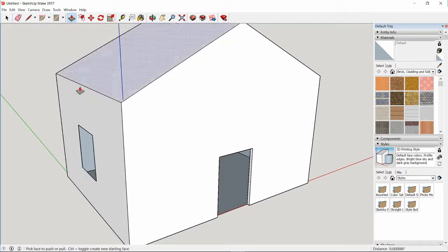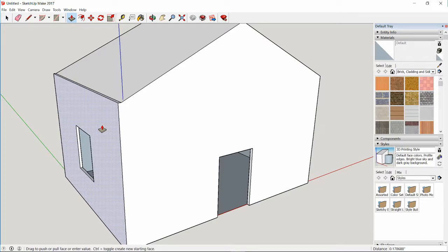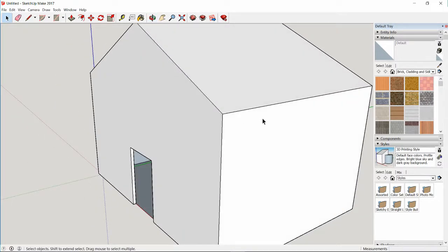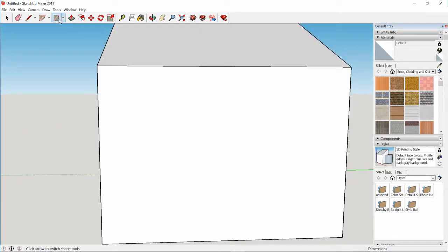And I guess it didn't feel like there. So I guess you have to make the window or the opening first and then extrude if you want this space there to not look 2D. I'm not quite sure why. But I guess because normally it's expecting you to make a hollow shape, but now that you have something in between, it's making these like edges, I guess. I don't know. So make the hole first and then extrude the wall, and we'll just pull this over again. And then we are going to do the same thing on the other side.